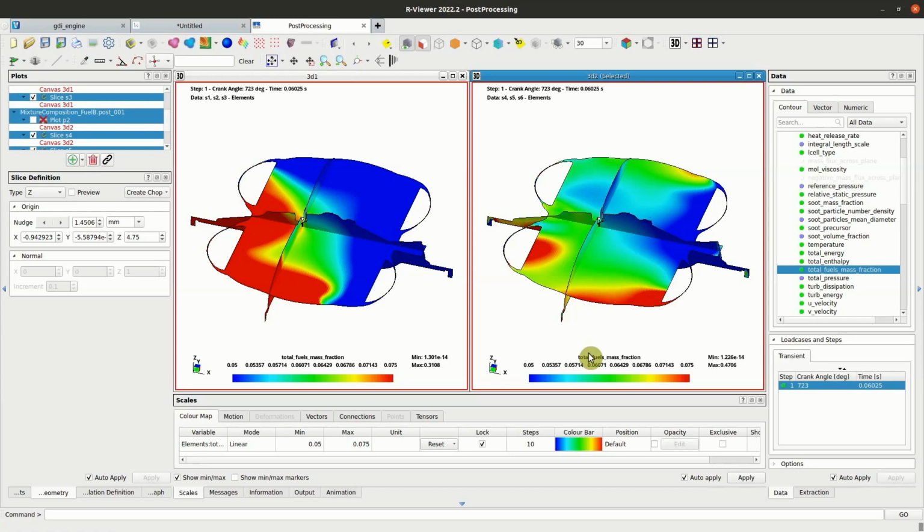The total fuel fraction represents the level of detail available when using pseudo-species instead of real species. All the fuel components evaporate in the same fuel species. Since we have access to the individual component concentration with a detailed kinetic simulation such as this one, let us look in more detail at the composition of the fuel B mixture.